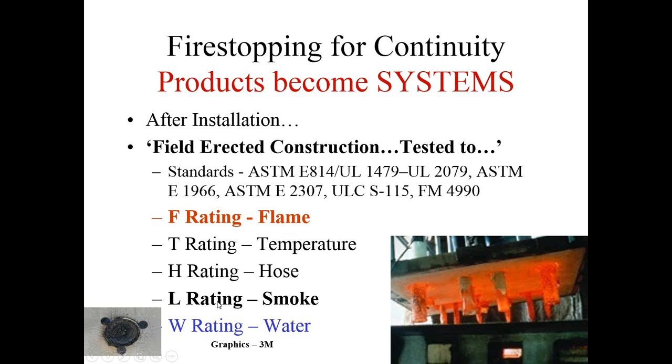The L rating is optional. It came in 1994. Friends of ours, Rich Walke at Underwriters Laboratories, and his team invented that L rating in 1994 to give a test standard that simulates the movement of smoke through the assembly. Basically what they do is put the assembly in a chamber, put some pressure on it, and then see how much air moves through in cubic feet per minute per square foot of opening area to give it that L